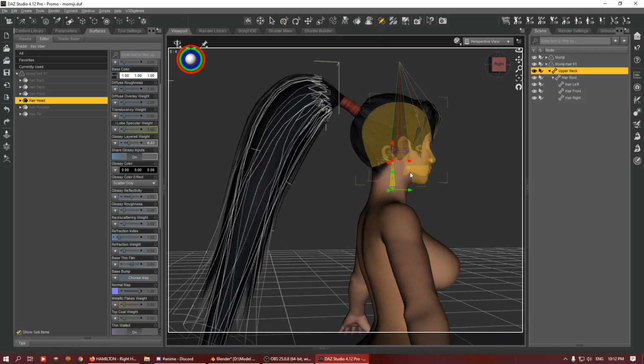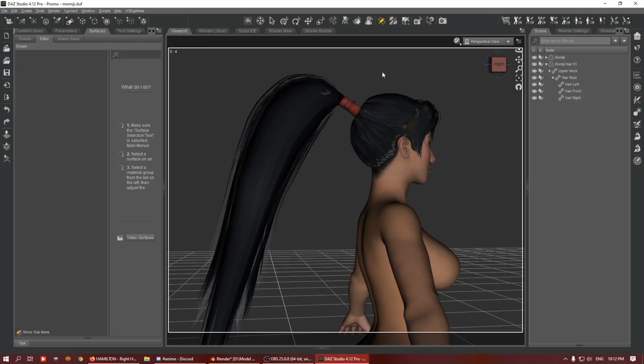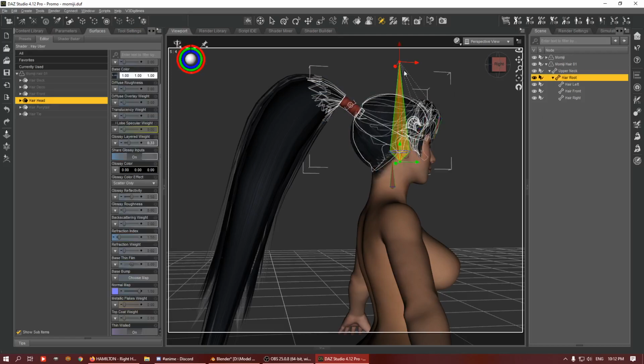So next, what you want to do, this basically applies to anything. For example, if you have clothing that has, I don't know, a front skirt or something, you can use this method to add additional bones to deal with that, right? How you go about it is you identify the root. In this case, I have a root file here. So next you do a create, right click, make sure you are in the bone, the joint editor. Okay, so right click, create, and create child bone.